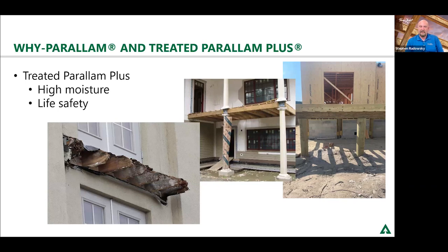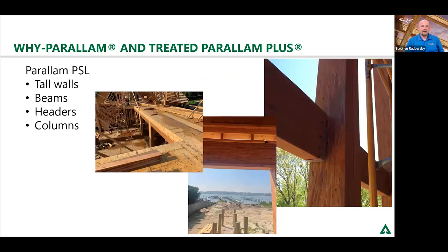So yeah, you'd really have to look at the design values and see what's allowed, like in commercial work or multi-family residential, like in 3B. I know that they want a solid sawn Doug fir for their exterior headers, where right now engineered lumber is not accepted. But hopefully that's going to change over time. I mean, every day we're moving towards more applications. The other great thing about Parallam is being able to get those long spans, and especially in tall walls.